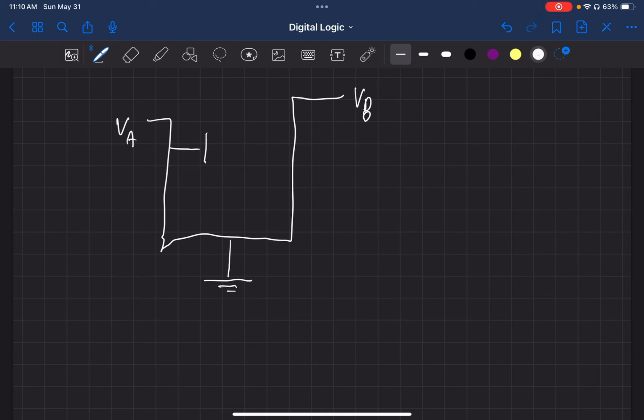We just have an inverter here and this being inverted there. So what we're really doing is using a race condition to our advantage. Whichever one of you is sending a stronger input to your corresponding gate is going to win and set the other one to the opposite, and that's the feedback loop.